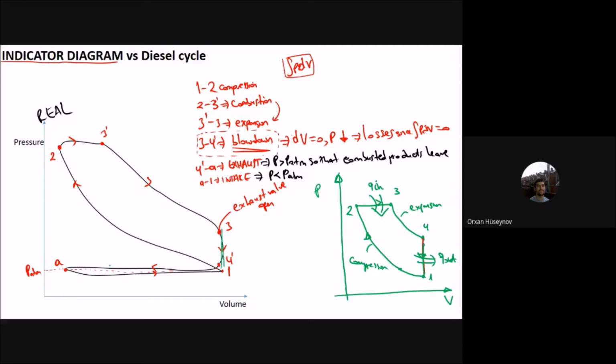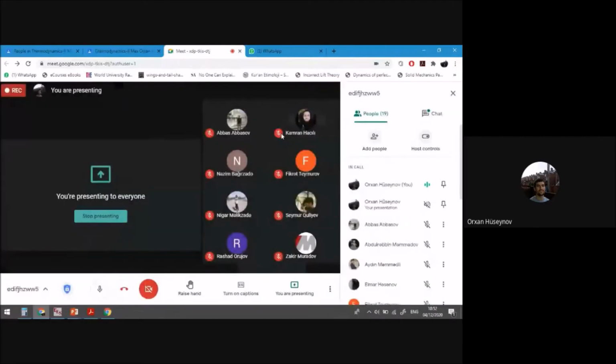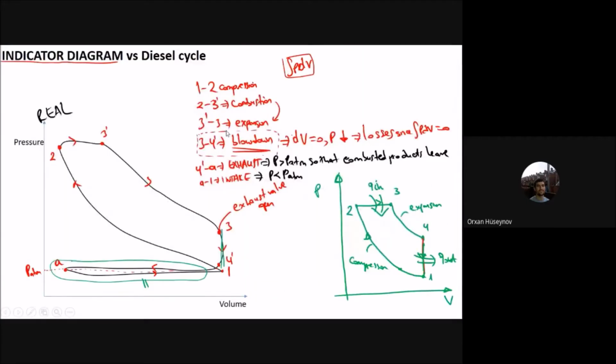And as we have said in our last lecture, this part where you have the intake and the exhaust strokes, these works cancel out because this is approximately symmetrical. And since it is approximately symmetrical, the positive part cancels out the negative part. You don't have any work output, approximately. Okay. Good. So we have it. And then now we will do a simple example. Then this one is the diesel cycle.